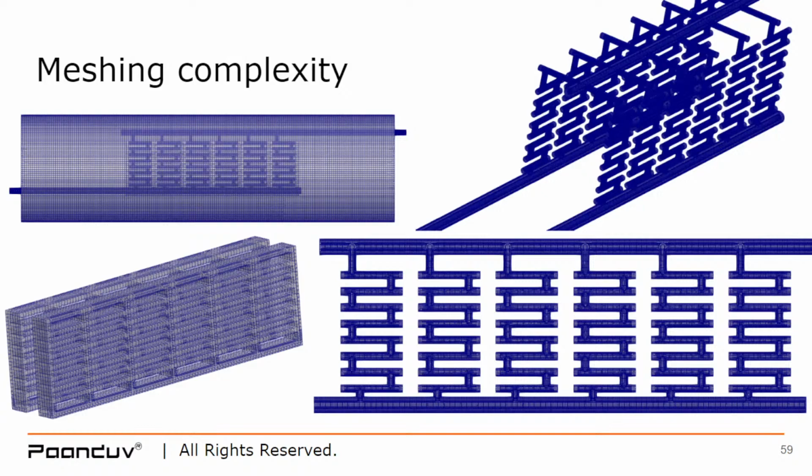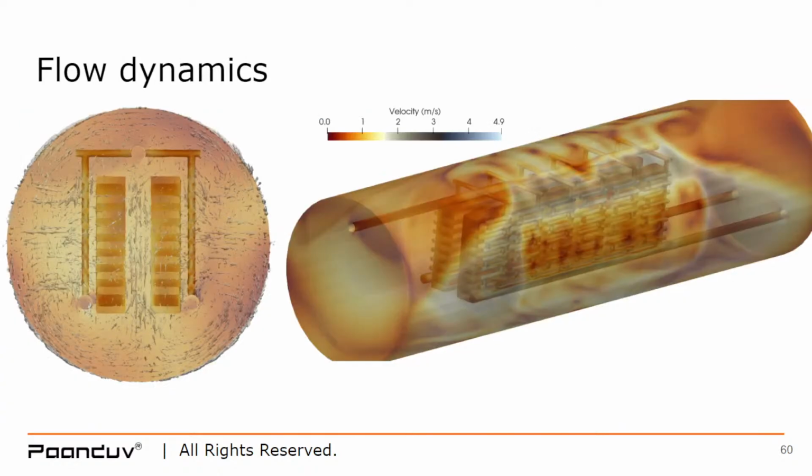So inside the heat exchanger with narrow tubes and channels, a much more refined mesh is used compared to the outer and bigger parts of the data center. Right. So again, we'll focus on two aspects: one, the flow, and the second is temperature. So let's look at the flow dynamics here. You can see on the right hand side how the velocity distribution is happening. There's a lot of buoyancy and convection happening.